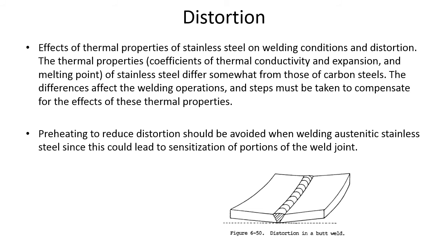Like I said, I've never really welded stainless steels a bunch, but I worked out at the Hanford nuclear site and everything was stainless steel, and we did a lot of really thin wall pipe. Some buddies of mine who were pipe fitters were constantly fighting distortion with this stainless steel pipe and tubing, just because stainless is really squirrely. Sorry for you guys in India and wherever. Squirrely just means the material doesn't behave the way you'd think it would. It just kind of has a mind of its own when you're welding it.